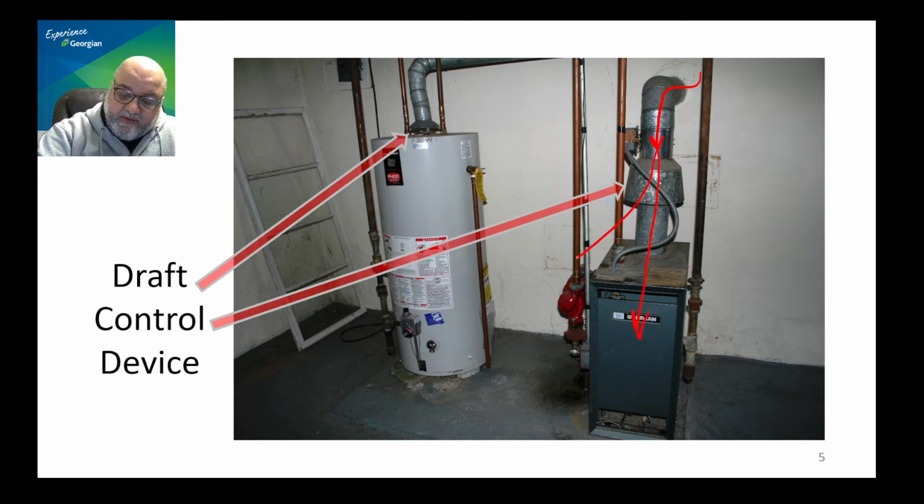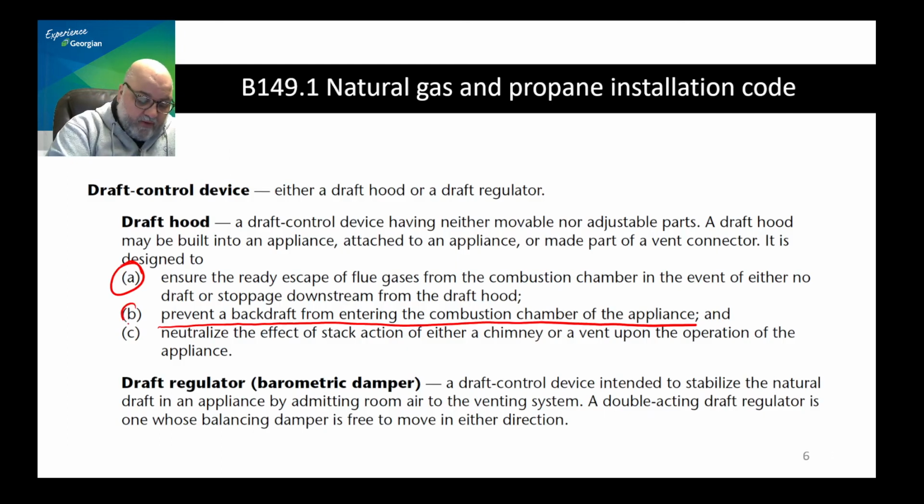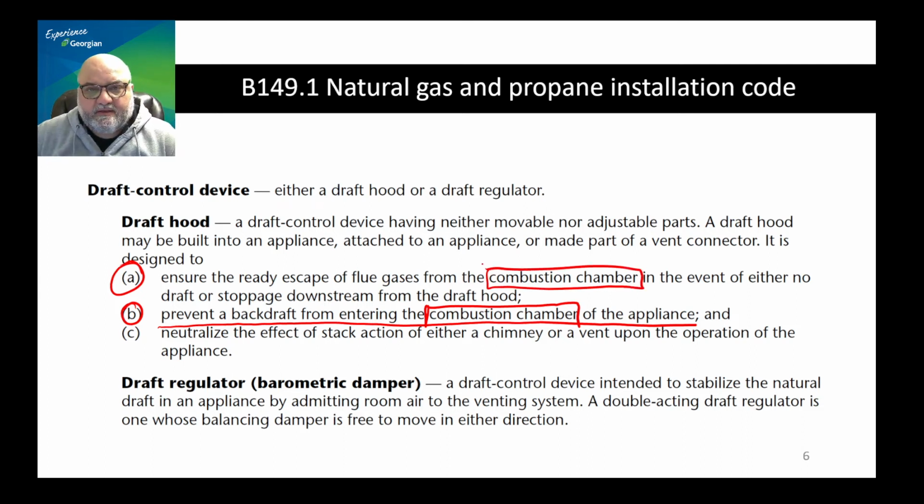You want it to be diverted to outside of the appliance. Similar to the first point, this point is also something that allows the combustion products to get away from the combustion chamber. As you can see, allowing combustion products back into the combustion chamber seems to be something that the designers are avoiding at high cost of spilling it into the room. There must be a reason for that.